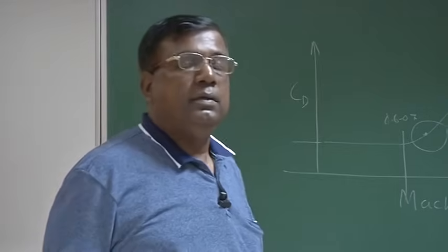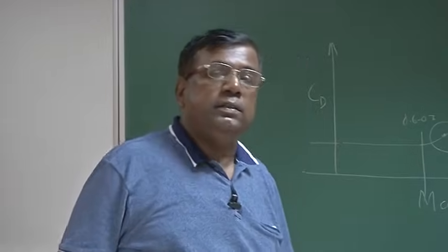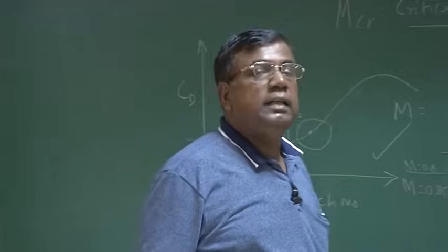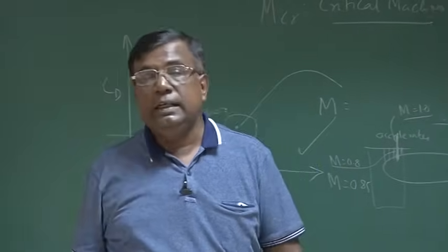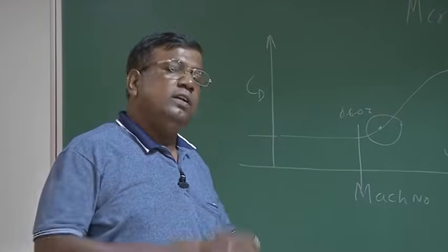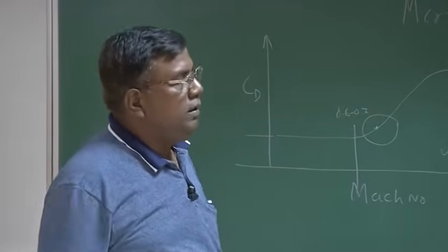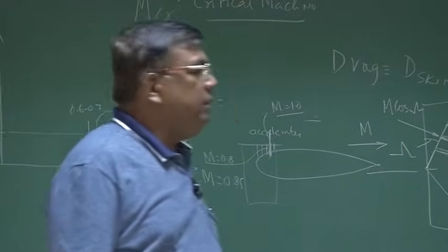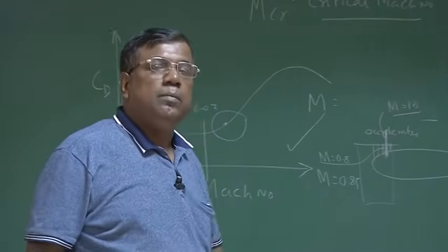But doing that, you should also understand you have the additional load of mechanisms which could reliably do this at all times, number one. This also amounts to an increase in the weight, and increase in weight always has an adverse effect on the performance. So the designer has to do all this sort of systematic, sensitive analysis and find an optimal or near optimal solution.